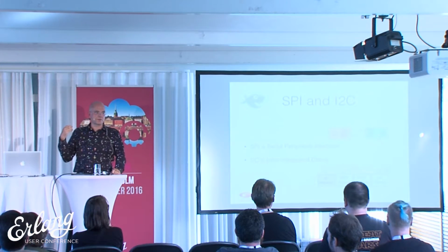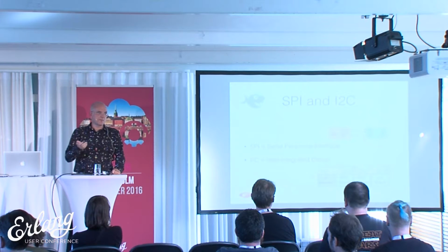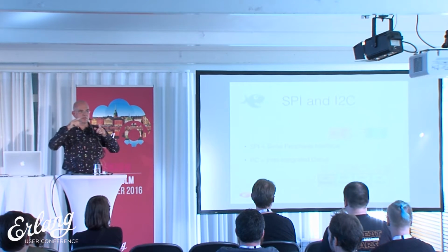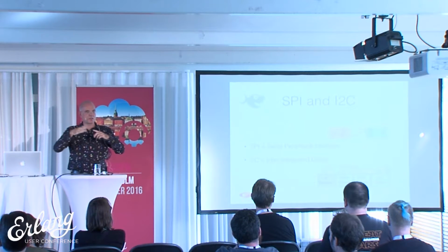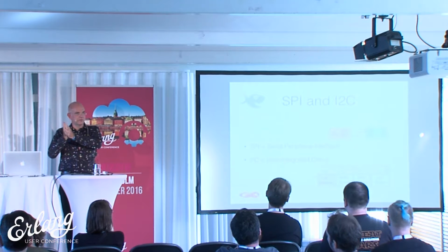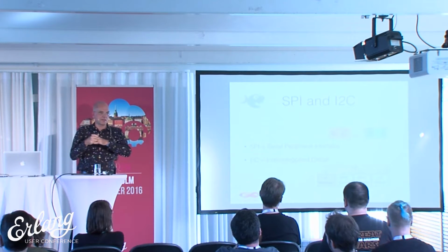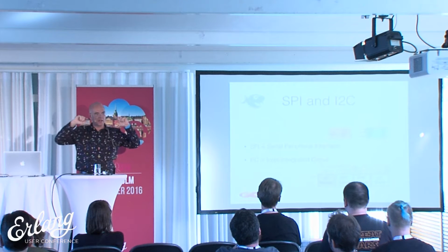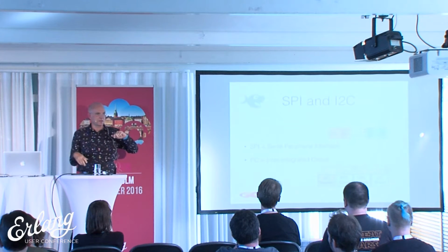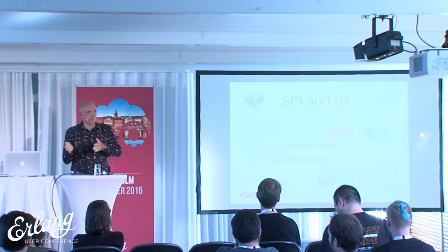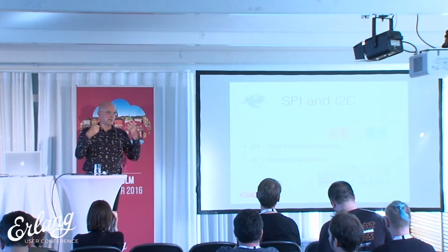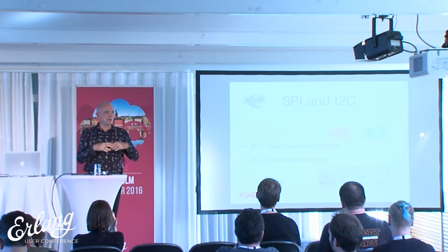And then, so you know what the timing is, there's also a clock. You need to configure, because every chip can have different settings for on which edge of the clock it changes the data and on which it reads the data. So there are 4 combinations: basically, inverted clock or normal clock, and rising edge or falling edge. What one needs to do is look up what the actual chip wants, and set one of the 4 options, and then off you go.